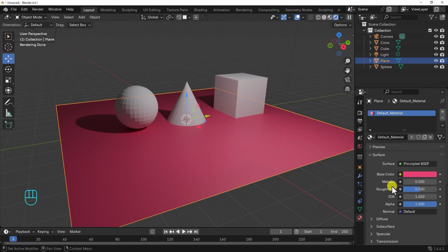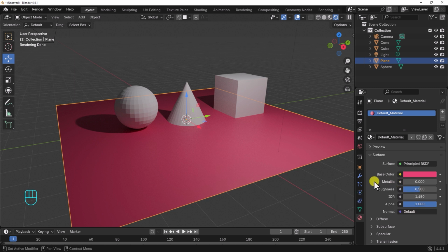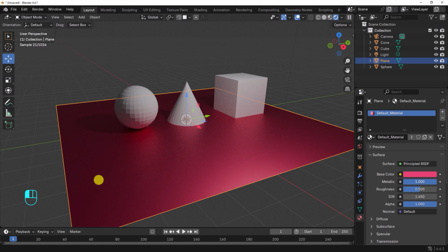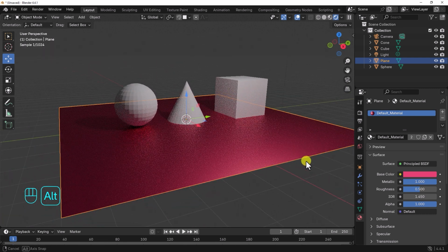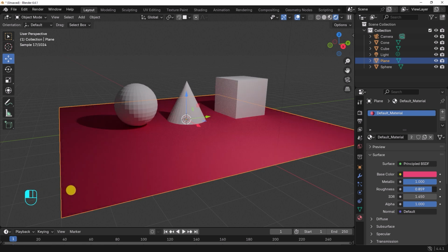I'm going to leave this as is for now, and I will show you a more detailed node-based materials editor in just a bit, which will have you feeling right at home if coming from a Hypershade or other node-based PBR material editor such as Unreal Engine. For now, I'll just quickly pop through these default settings. Let's slide the metallic slider to 1. And that gives our plane a metal look. We can adjust the roughness/shininess and make it a very shiny plane or a much rougher one, and so on.